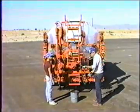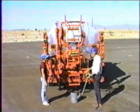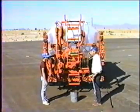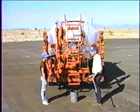Okay, we have been spraying and we've done all of our handwork. It's time to clean it out. We've got diesel in the bucket. Put the pump into reverse. We were running in forward. Put the pump in reverse and speed it up. This full speed reverse is fine.